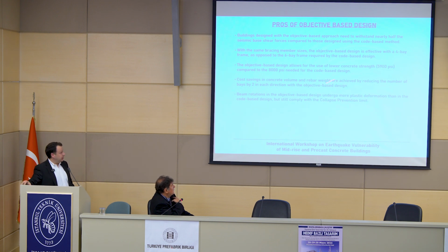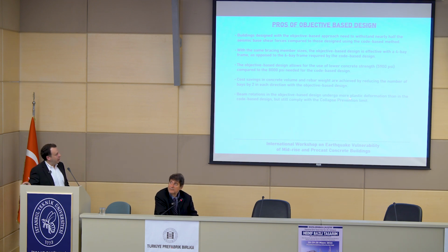And then, the beam rotations in the objective-based design were a little bit larger, so we did have a little bit larger plastic deformation than the code-based design, but they still complied with the code objectives and were still very, very reasonable. I think the maximum was 1.6% rotation there. So we were able to achieve slightly larger deformations, but overall a much better and cheaper design.